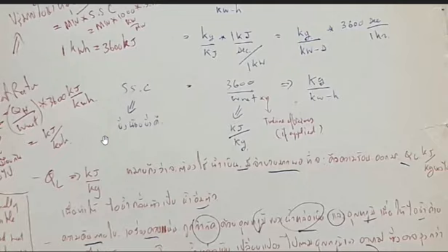The importance of the heat rate is that we can use it to determine how much coal we need to provide in order to give enough heat to the steam to produce the amount of electricity that we need, because the heat rate says the amount of heat in kilojoule that we need to produce 1 kilowatt hour, or 1 unit of electricity.